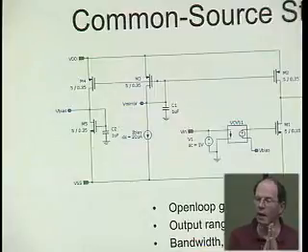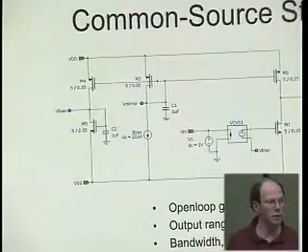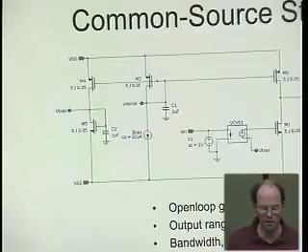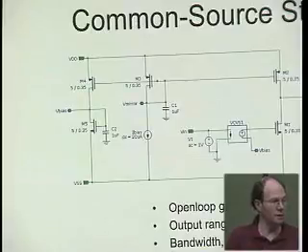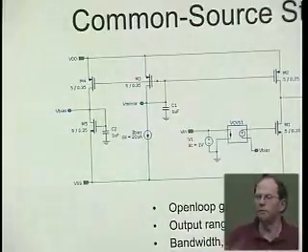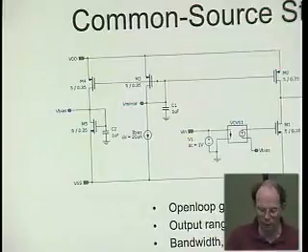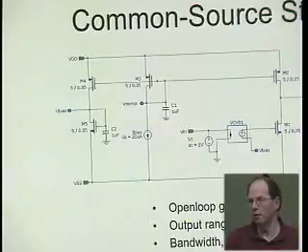And of course, the simplest circuit to implement that and therefore to analyze is the common source stage. So we go again through the common source stage and look at all the performance metrics. It's very simple. We can put together our test circuits to investigate this, much simpler than having a monstrous amplifier where always something breaks and gets in the way. And then afterwards, when you have the big one, well, we already know how to evaluate it.